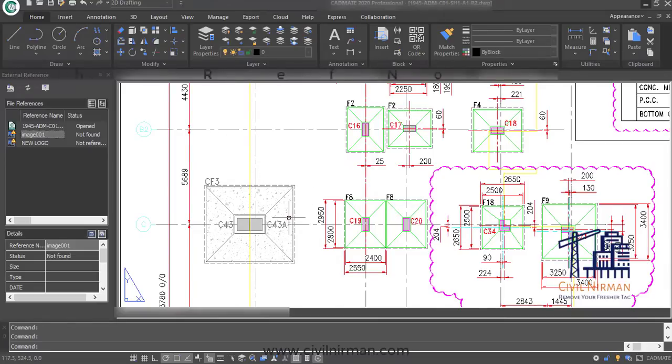Tip number 12 is that you need to check that if this particular drawing is separately developed, then the reference drawing number for this existing structural foundation should be there as a reference in your drawing, right? So you need to check that point too.